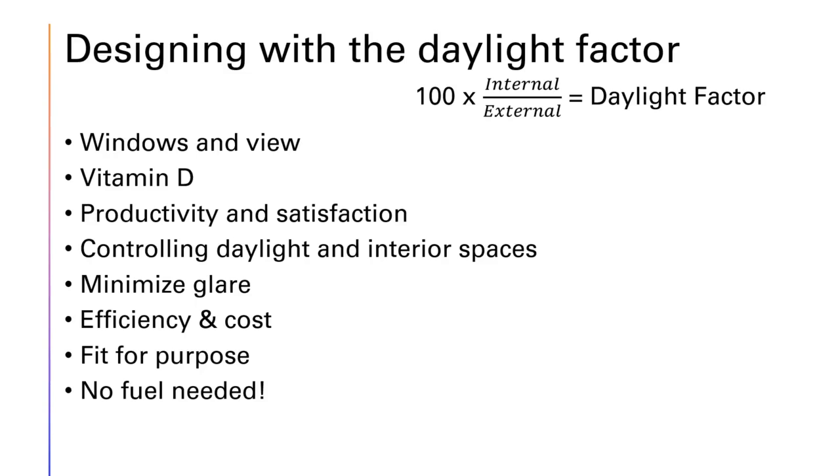Obviously, you want the surgeons to have a lot of light, and then it goes up to fine artwork with watchmaking. Could be, in jewelry production, could be 2,000. So with daylight factors, what it's actually saying is how much internal light can we bring in from the external. The more external light we get, the less internal light we need, which will be cheaper in the long run. It will be cheaper to run the lighting in the building.